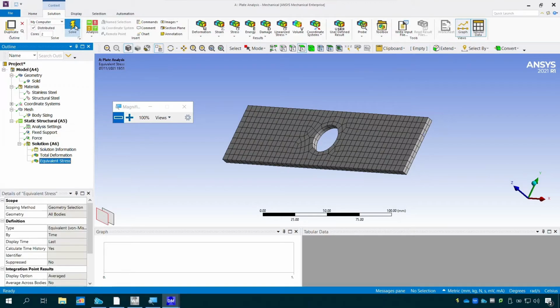So what it does, it will enable the Ansys solver, go and load it, which basically you can see the solver is trying to solve it. It goes to the main brain of the FEA solver, tries to calculate for you, and depends on how complex a geometry you have, it might take longer. For instance, here it is really simple, it shouldn't take that long, but if you have a really complex model, sometimes it takes a few days, a few weeks, or even a few months, depending on how much computer power you're looking for, what's the quality and size of the mesh, what's the geometry you have, what kind of supports, what kind of loads you have.